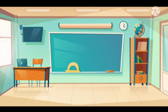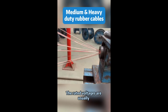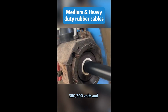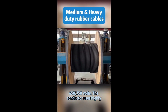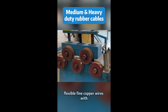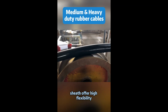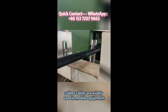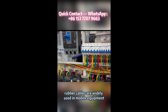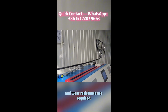Medium-duty and heavy-duty rubber cables are generally available in 1 to 5 cores and multi-core structures. The rated voltages are usually 300/500 volts and 450/750 volts. The conductor uses highly flexible fine copper wires with stable electrical performance, while the insulation and sheath offer high flexibility, abrasion resistance, and oil resistance. Therefore, rubber cables are widely used in mobile equipment and construction machinery where flexibility and wear resistance are required.